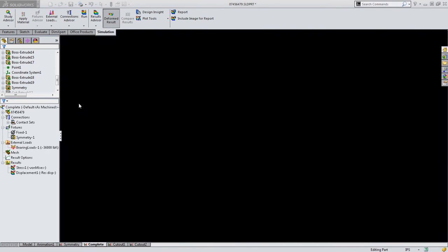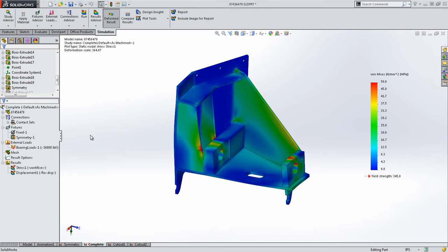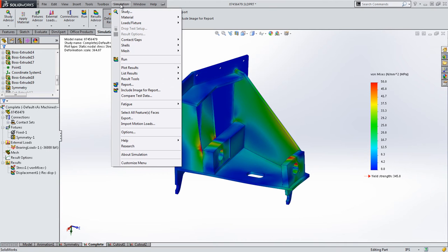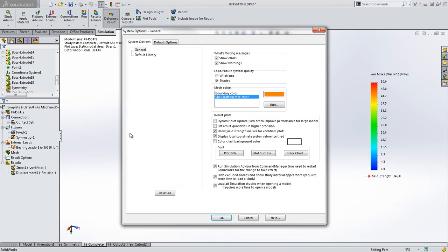We've also got some enhancements for performance. In the simulation settings now, you can control when results get loaded. So if you are working on a lot of SOLIDWORKS features, you can now turn off loading simulation results when the model is open to delay that extra overhead. So this means that you can have simulation active and it won't cause overhead when you're working on SOLIDWORKS operations.